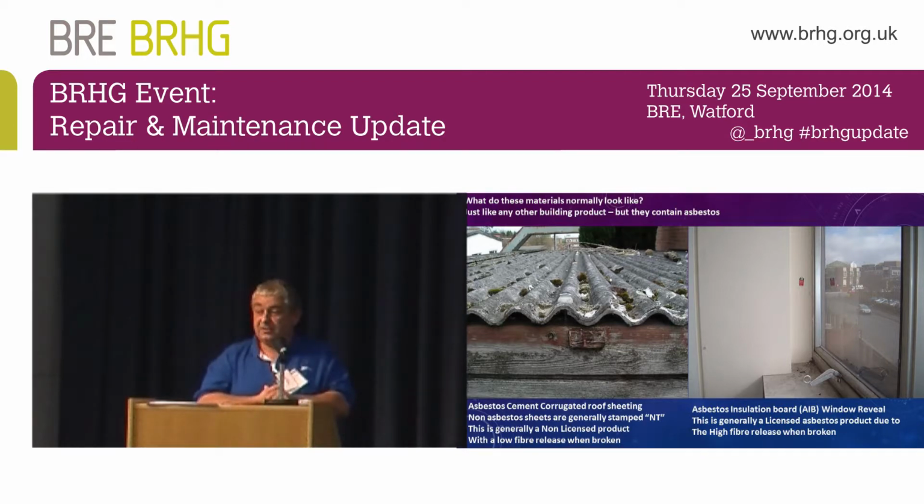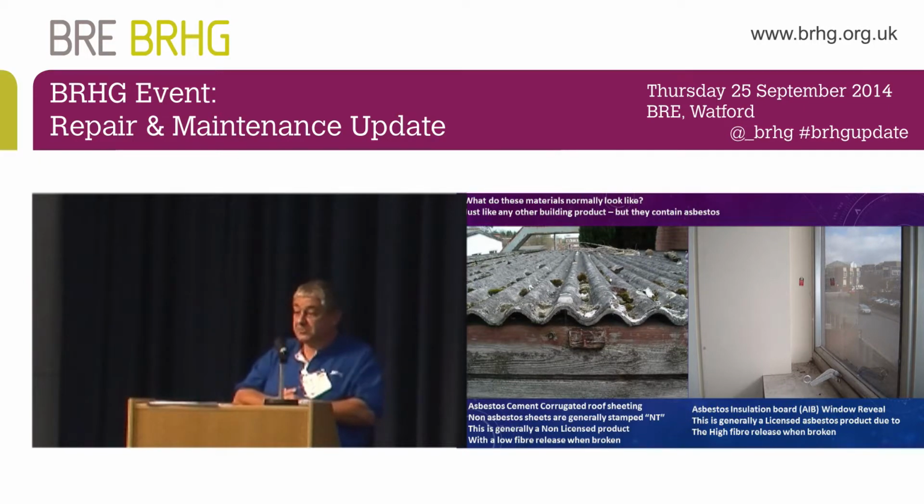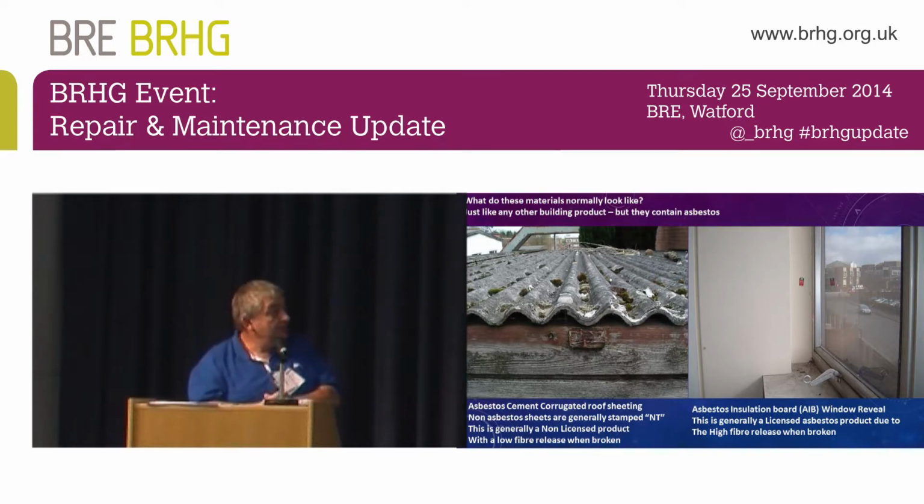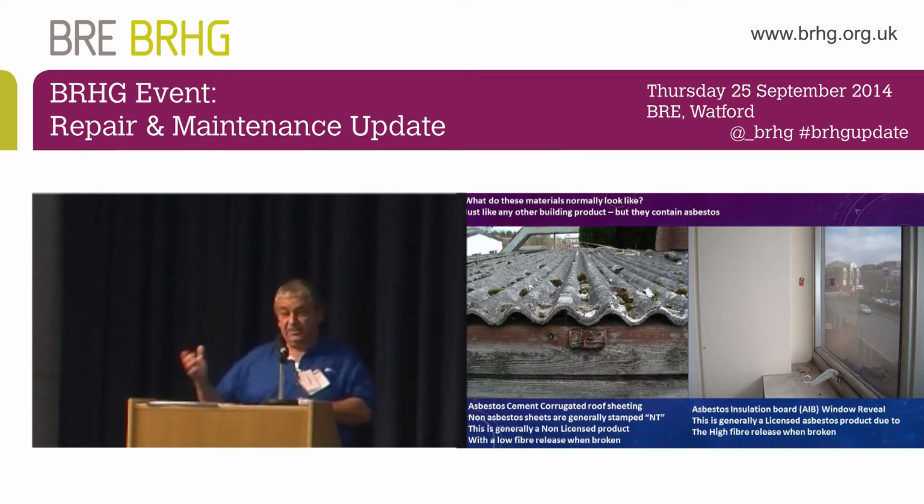It's generally one of the things that you can do as a non-licensed product. It's a low fibre release when it's broken. You still get some fibre release, but it's low. The worst problem when I'm doing risk assessments for people with this, especially the demo people, was at the Warner Brothers studios. They were doing asbestos cement removal there, and the directors were driving past every day, seeing clouds of dust as the guys were putting big diggers in and smashing the roofs down. Big problems. Can you come and have a look at this, Dave, and sort it out?